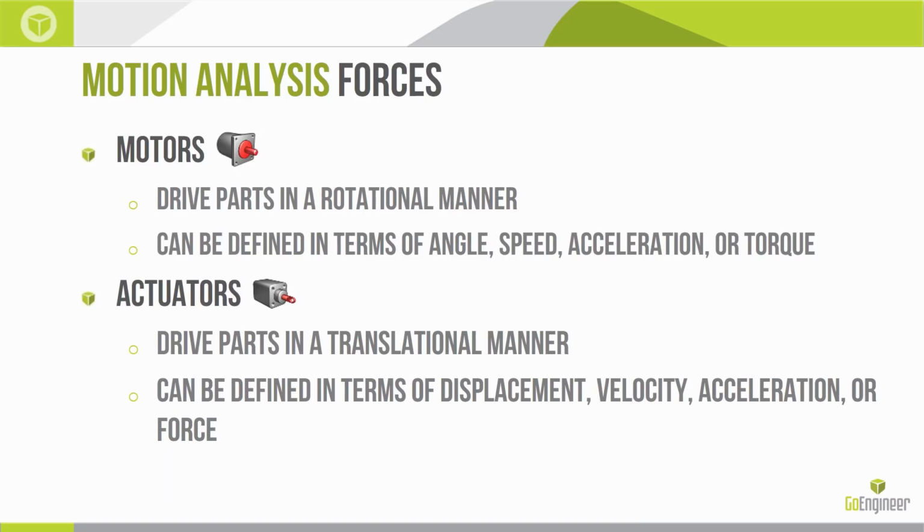Now let's talk about forces. Forces can be applied in a handful of ways. We're going to step through them. The number one way is motors. Motors drive parts in a rotational manner, and motors can be defined in terms of angle, speed, acceleration, or torque. Actuators drive parts in a translational manner, and actuators can be defined in terms of displacement, velocity, acceleration, or force. All just depends on, again, your design intent, what info you know, how the actual situation is going to play out in real life.